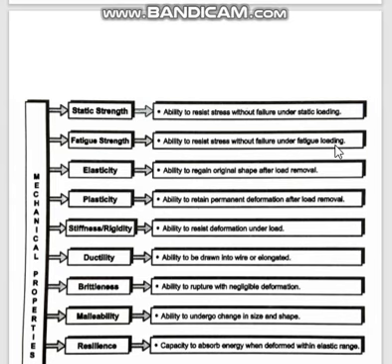Yesterday I told you that when a component is subjected to repeated loading, even ductile materials are found to fail much below their yield point strength. It is found that for an infinite number of cycles, say 10 to the power 7 cycles, if you keep the load under a certain level, it will not fail.